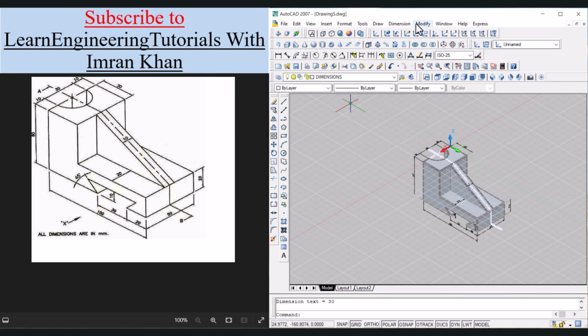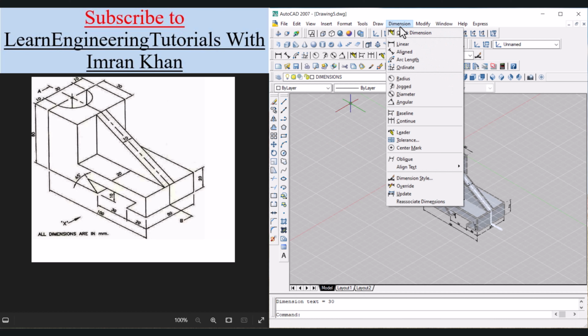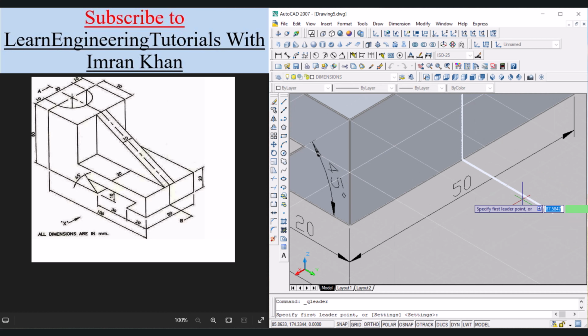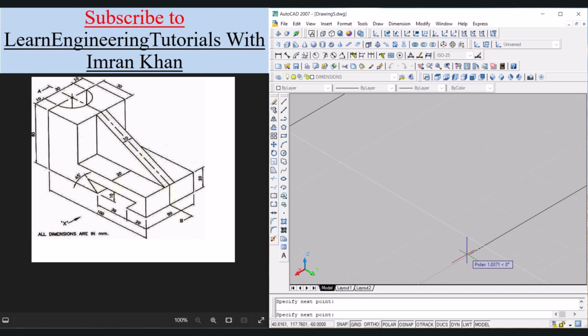So let us click on dimensions, click on leader line. Let us select the first leader point, so let it be this line. Click. So let's go in this direction, and when the tracking is shown, then move along that line and click. Move in the same direction and click again.